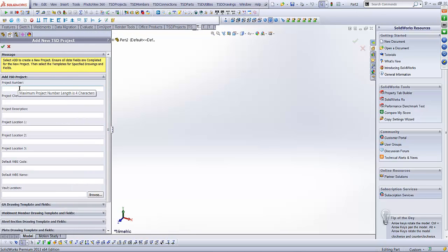Under the feature manager page, we've got to put in our project details, and the project details are actually carried over into the drawing sheets at a certain stage which we call lockdown. It's not actually a lock process, it's like a final process of creating drawings. So I'm just going to run you through the initial settings of what actually goes into a project and how the project's created. This shouldn't take any more than 20 minutes, maybe half an hour tops.